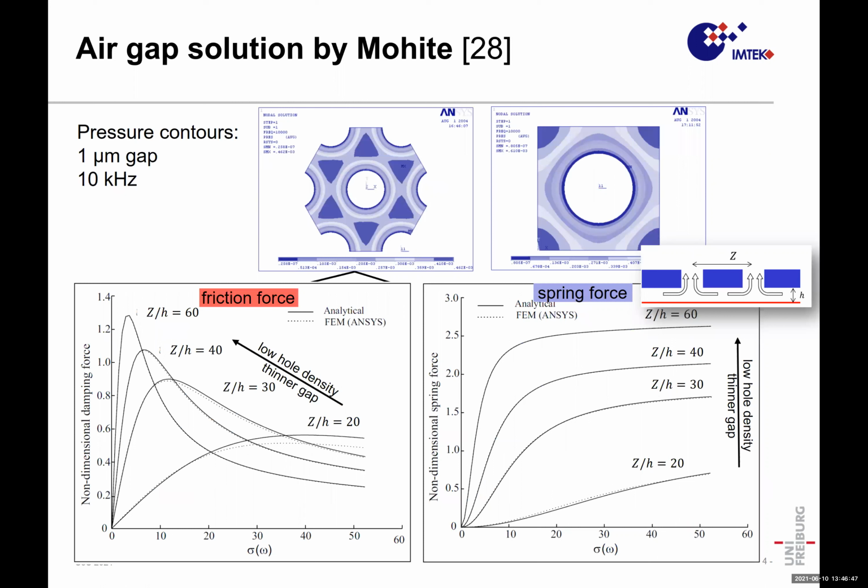Nowadays, people like FEM simulations very much and rather run an ANSYS than such an analytic solution. It's a more modern situation where we see the pressure drop along the holes. It is a unit cell, hexagonal. He could have also done a trigonal unit cell, I would say, and spared some computational time. Of course, between 3 holes in the center, the furthest apart, we have the higher loss from there. And if you compare to the square situation, the loss is a little less. And then we find descriptions for friction and spring losses out of this.